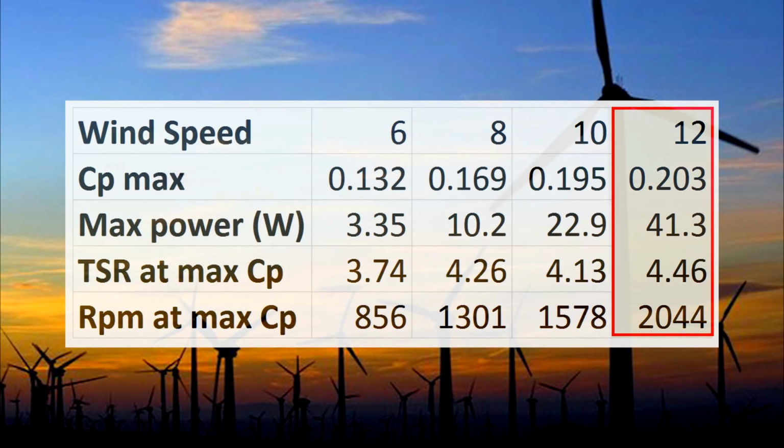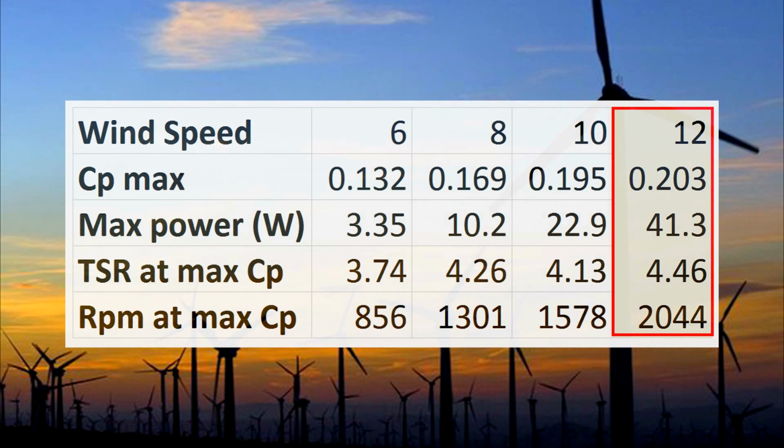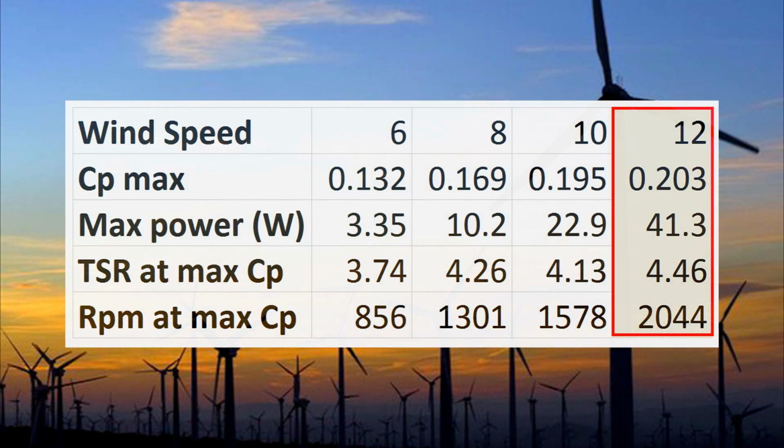Overall, our wind turbine achieved a CP value of 0.203, while we exceeded our design TSR by 0.459. Our CP value and maximum power output is lower than our calculations due to factors such as friction, flow separation, and losses due to the wake. The TSR of the wind turbine may also be affected by design parameters such as the tubercles, which were not accounted for in our calculations.